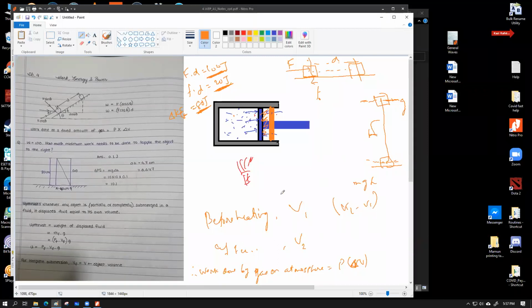But for the earlier case, efficiency is not applicable because I defined this piston to be frictionless. So this is another setup scenario. In this case also we can say work is being done on the system. We are externally doing some work on the object by pushing it, and the net work done on the object was 80 joule, because 20 joule was wasted due to the frictional forces. That 80 joule of kinetic energy would get stored within the object at the end of the displacement for which we applied the force. That's the basic idea. So in this case also work is being done from the external source, so work is going into the system, or the energy of the object is increasing.